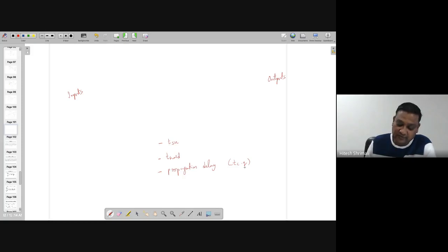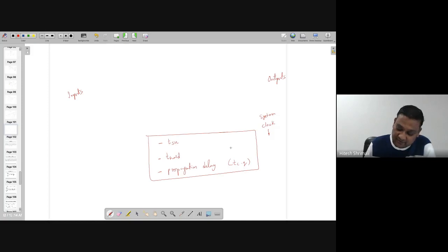So we have to manage all these things, and accordingly we have to decide the clock. Sometimes there is a system clock, and from the system clock you derive different phases of clock. So that has to be more than what is listed over here. Nowadays jitter is also playing an important role, right? Because you're going to very high speed, so jitter will be there.